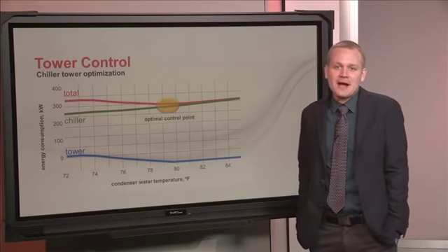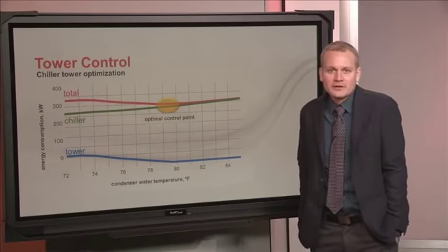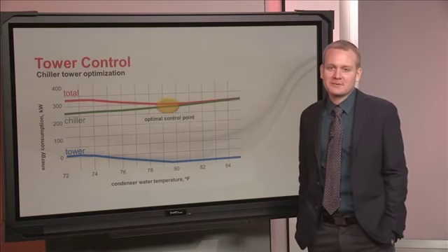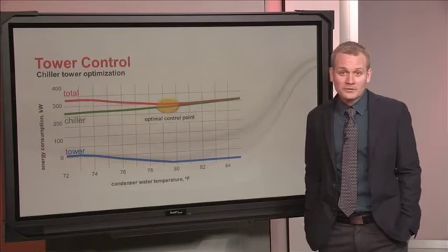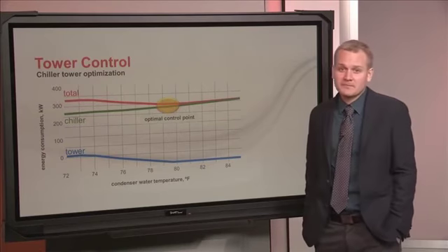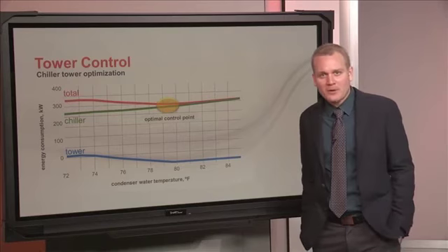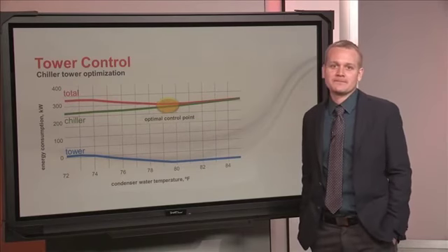In the future, if you need a reminder on how any of these controls worked, click on the FAQ tab in the lower left corner, and you'll find a detailed explanation of each control. Also note, if you choose an air-cooled condenser, this section will be completely hidden. We simply use the hourly ambient dry bulb as the input for the chiller condenser.